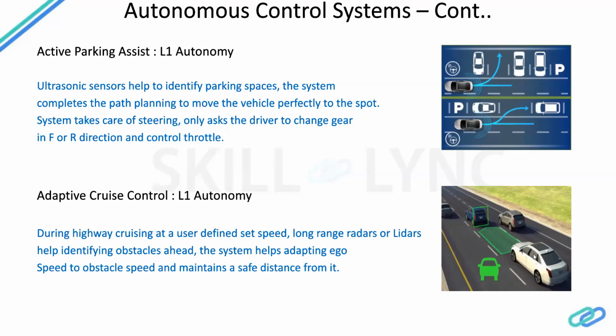At the moment you do a little bit of steering and put on an indicator, the control model will understand this person wants to overtake. So it will apply more throttle so that you can overtake this vehicle, and then again it will drive at the set speed that you set, 80 kph, until another slow moving vehicle comes in front of you in your designated lane.